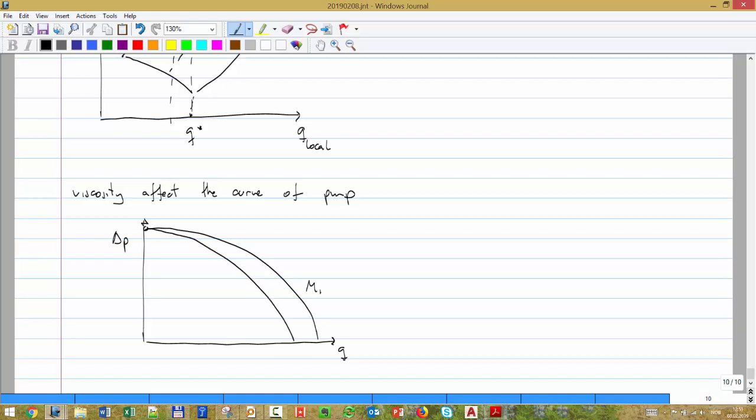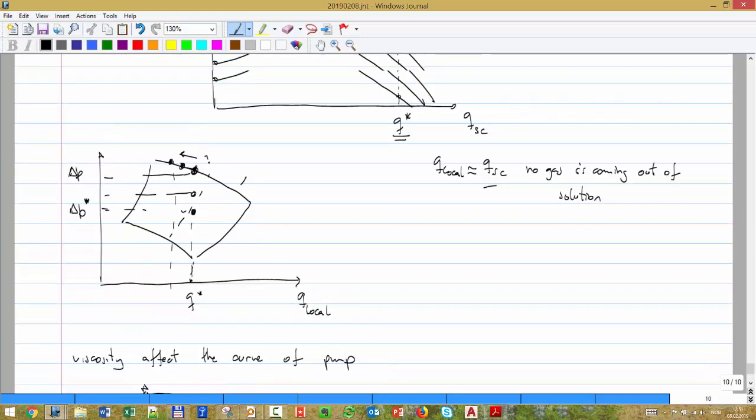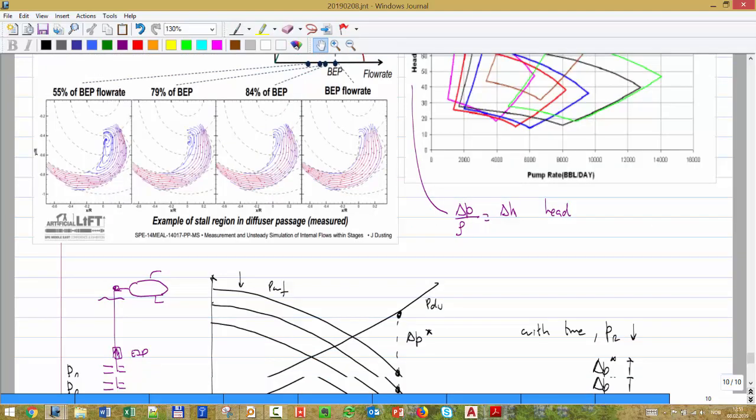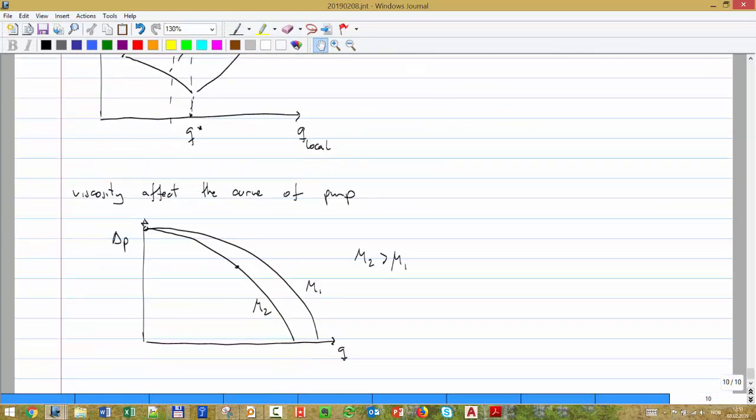It is an effect similar to the frequency. When you increase the viscosity, you get less delta P from the pump. That's because the fluid has to go through all of these passages in the blade and in many places, and you simply have friction losses. So that's why, when you have viscosity, you also have to change the shape.